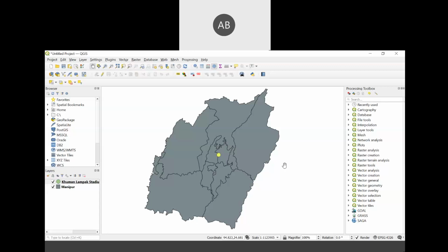How can you find out the location of your house? One way is Google Earth. Okay. Another one, you have a GPS. You go with the GPS and then find a particular house and then read those coordinates and then you plot those coordinates in an Excel file as latitudes and longitudes, and then try to import that file onto the GIS.